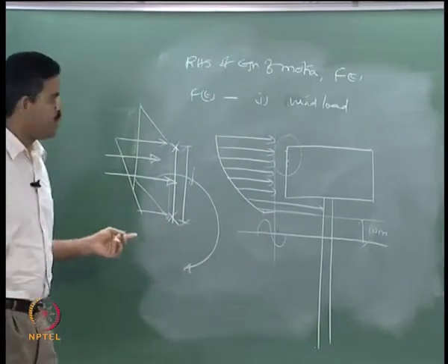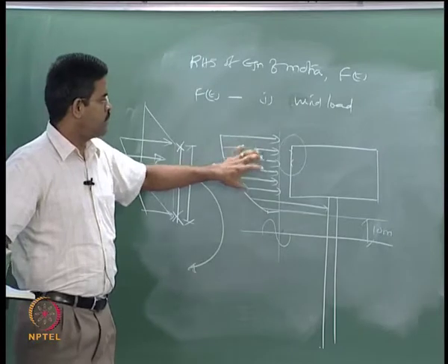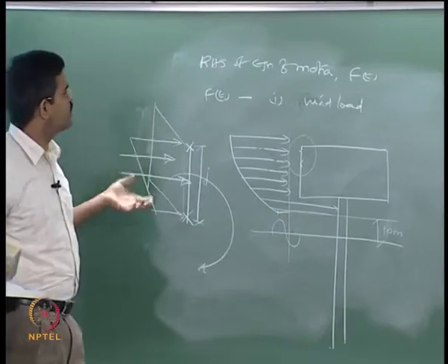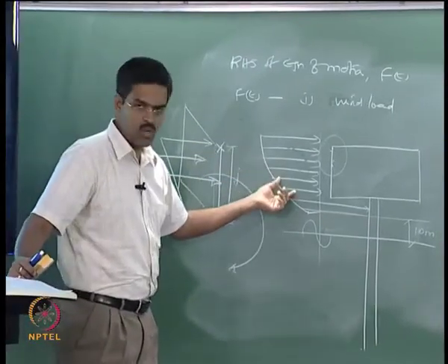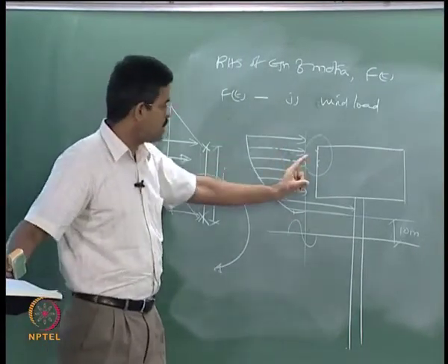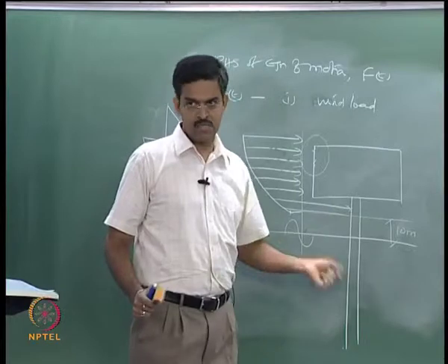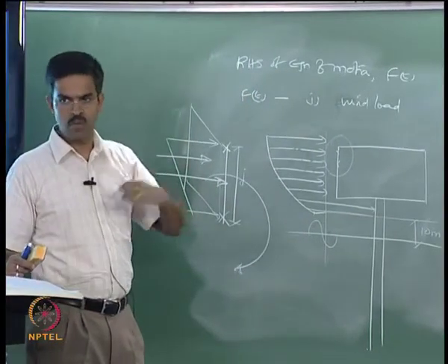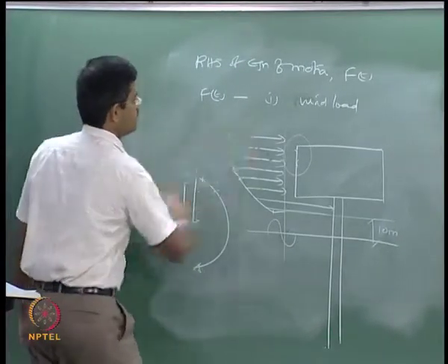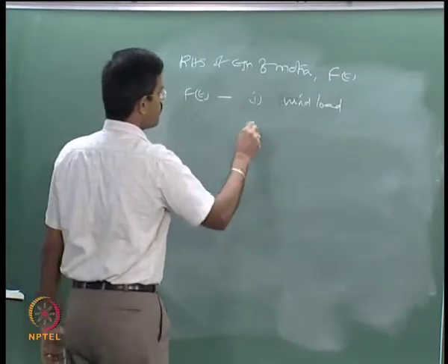Any doubt here? I am not explaining this governing equation because we already have this power law given to you. I believe that you have read this and understood how it has been computed. This is a scheme of how it has been done. So I think there is no difficulty in finding f of t because of the wind load on any member and any element you want, because all these are not forces, these are moments about the base. Why are we talking about moments? Because my displacement degree of freedom is not x, it is theta. So I am talking about all moments because I am talking about rotation. Is it clear? I will remove this. The second force of course we have is the wave load.